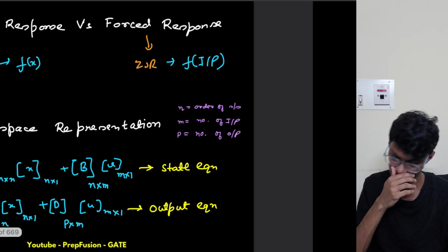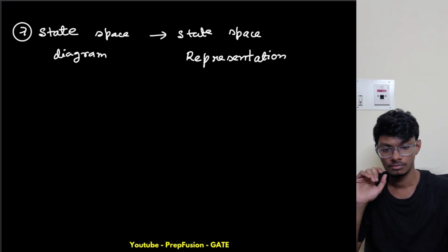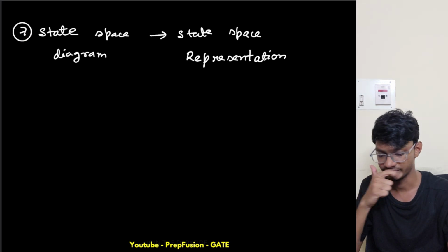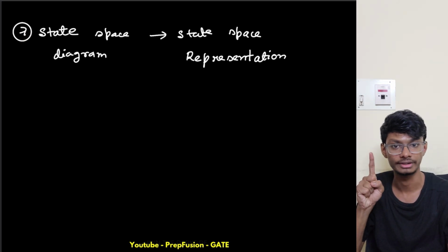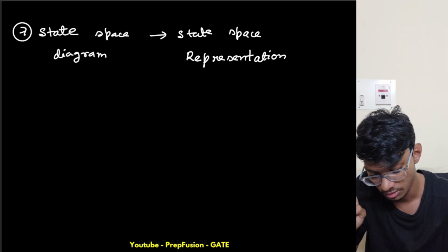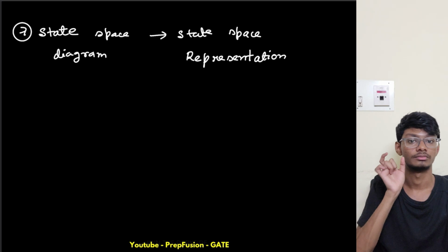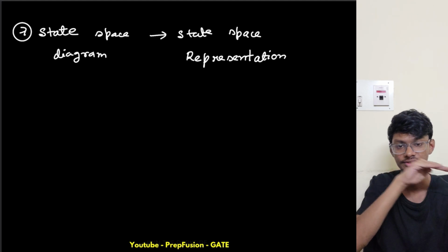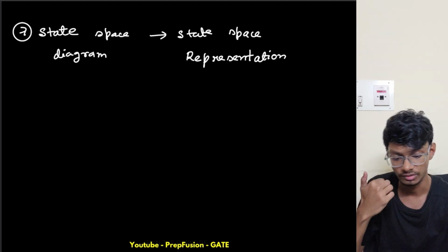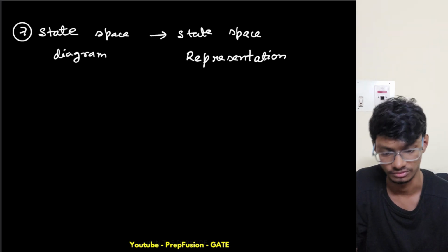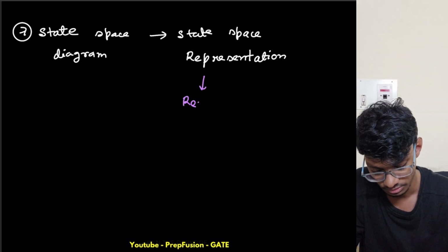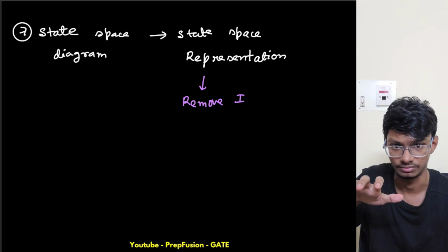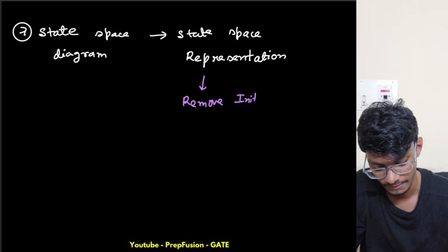Okay, so right now, there was some procedure there, we wrote the cause effect relation and all those things. What is the procedure here? Remember, right? What was the first step? Was it to write the time domain expression? No, right. Was it to delete the integrators in the SFG? No, it was to remove the initial values. So if there are some initial values, the first step was to remove them, because in the representation the initial values don't come. Okay, remove the initial values.